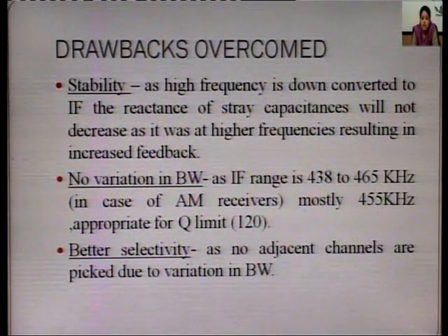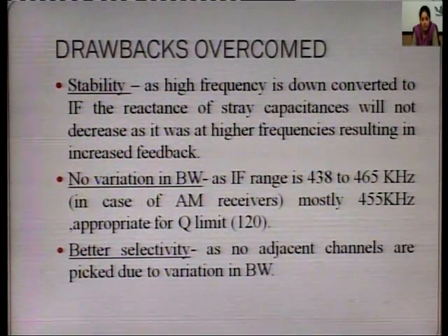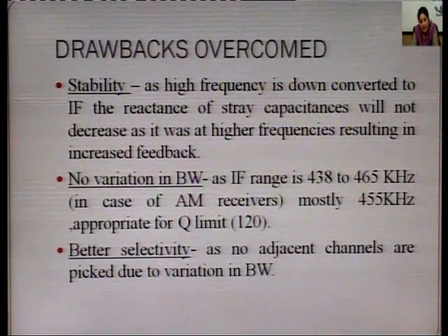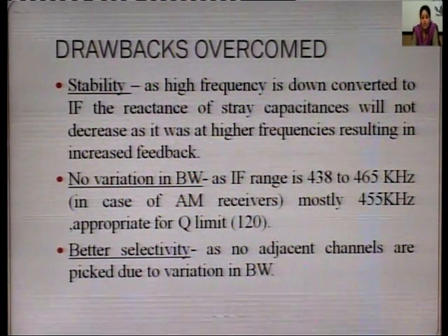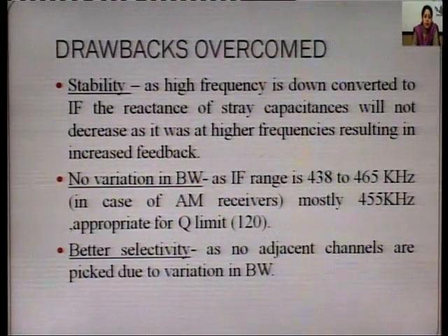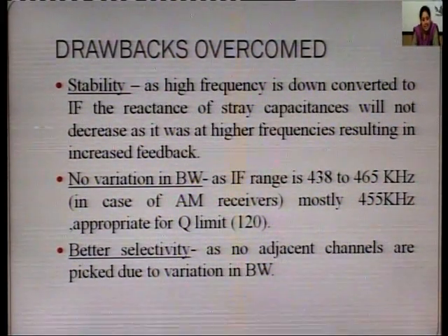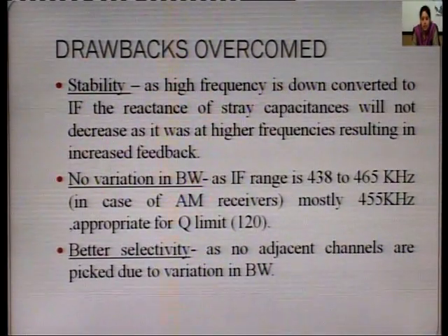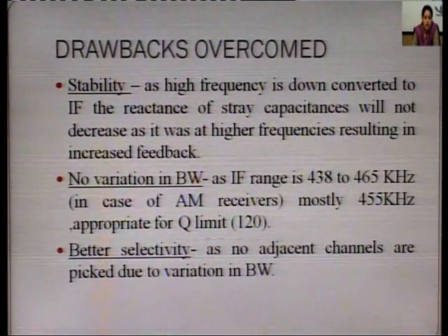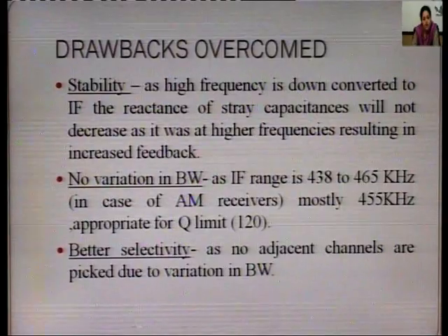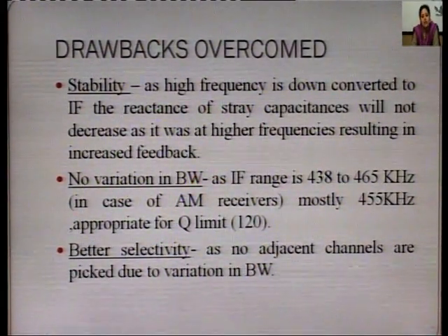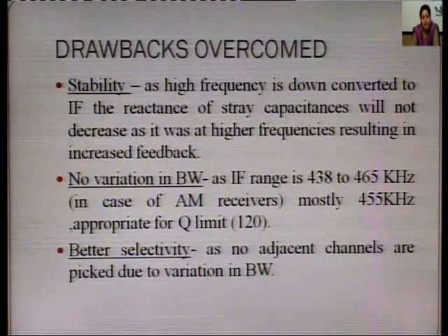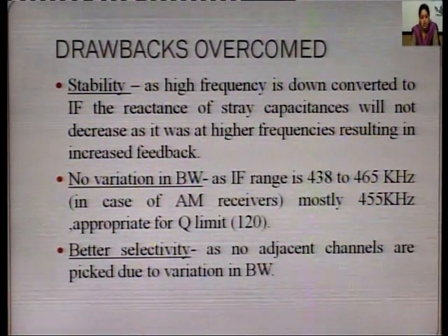In the TRF, the reactance of stray capacitances decreased, resulting in increased feedback, and that positive feedback resulted in oscillations. But in this case you are not having a high frequency, so the reactance of stray capacitances will not decrease, there will be no increased feedback, and in turn no positive feedback that would result in oscillations.